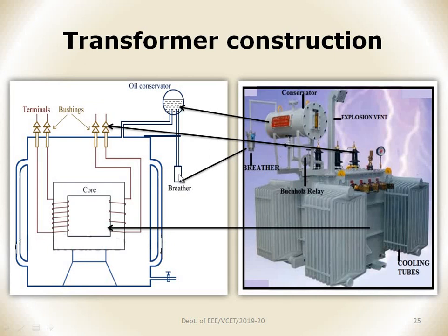The breather is filled with silica gel. By the change in the color of the silica gel, you can find the level of moisture content present in the oil.